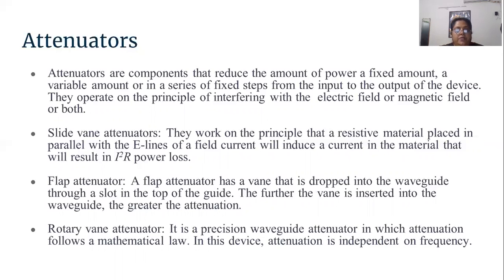Rotary vane attenuator. It is a precision waveguide attenuator in which attenuation follows a mathematical law. In this device, attenuation is independent of frequency.